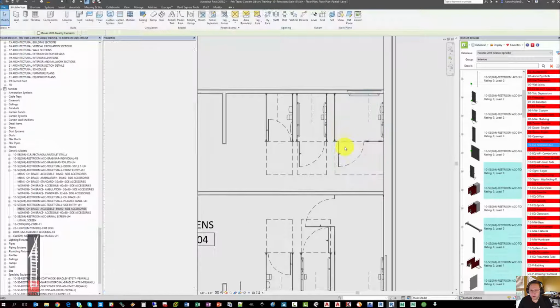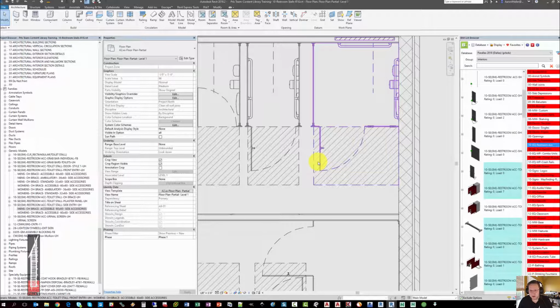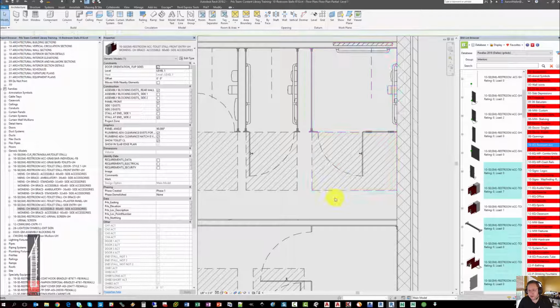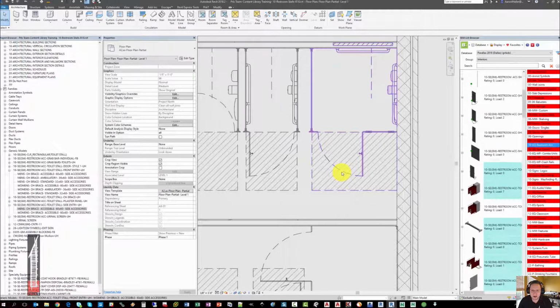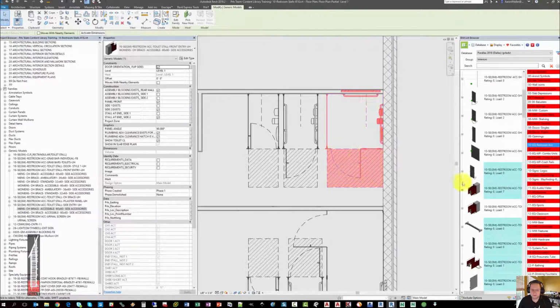Zooming out and looking at the stall, the door currently is not in the appropriate position, as this would make it difficult to exit the stall and have to maneuver around the door. All of the stalls have a parameter, instance-based, that is door orientation flip sides. Checking that box will flip both the door and the robe hook to the other side so that we can have them opening in the correct direction.